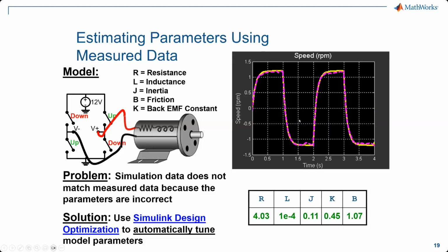Now, what have we achieved at this point? We have taken three steps. First, we identified the object that we want to model. We're using the first principle method or the data-driven method. We developed a model which behaves the same as the physical asset. Third, I compared the actual data from the hardware with my simulation output. If it is not the same, I did one step called parameter estimation, and then I tweaked these values. And now the final motor model that I have is the actual plant model of my motor.